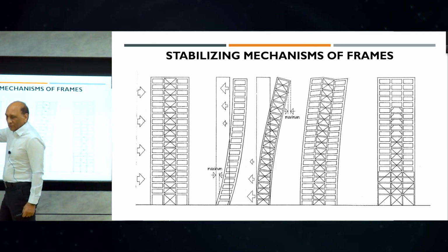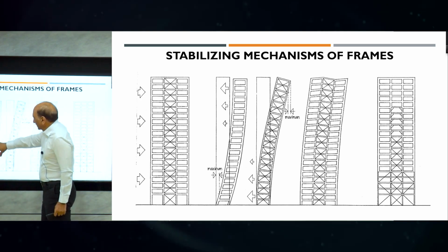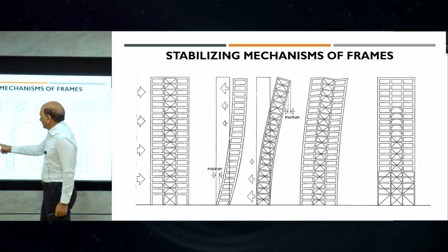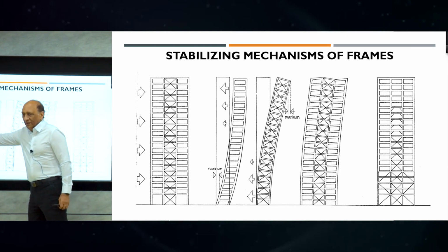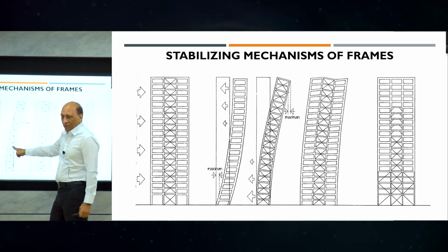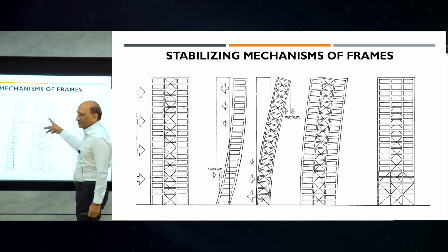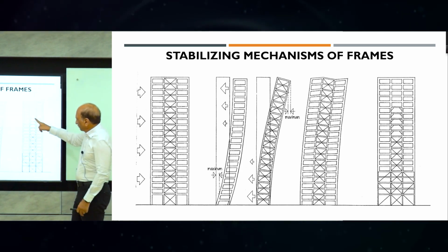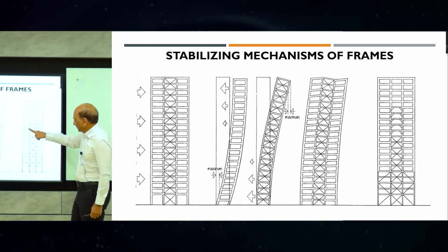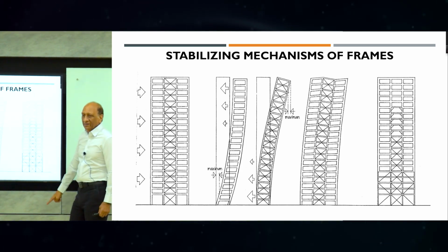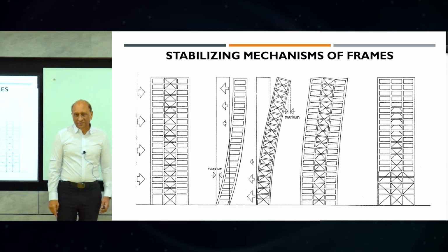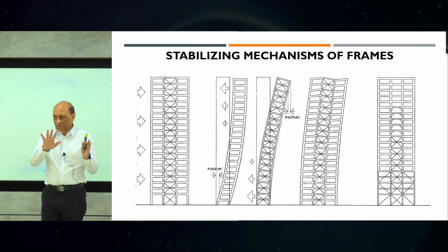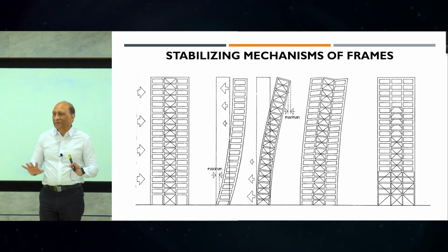If you don't couple them together, they will bend like this. When you couple them, this will act like a frame and this will act like a wall, and when you combine them together, it will act like this one. And then if you want to brace it locally, you can brace it that way too, gradually increasing the bracing as you go down, because the deflection is accumulative.